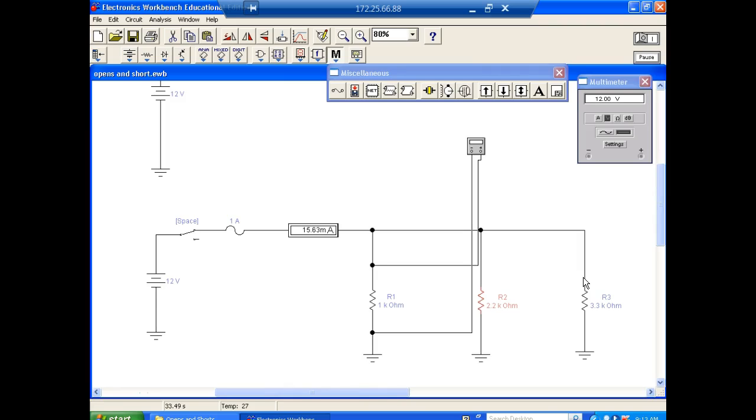But your house is wired in parallel. So this is why we can do what? We can plug stuff in. When we're through with it, what can we do? Unplug it, right? And when I unplug it, it doesn't consume any power, so that power is not added to your power bill, right? You understand that? So on a parallel circuit, every short is a short circuit, and every open is not necessarily an open circuit. How would I get an open?